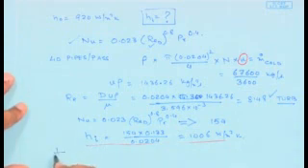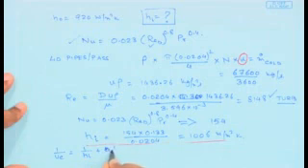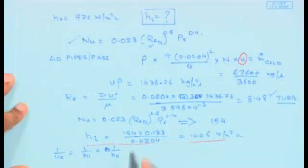So, 1 by UC, the clean coefficient, the overall heat transfer coefficient based on the clean condition. So there is no effect of RD or the dirt factor, it is just the algebraic sum of the resistances of the convective heat transfer resistance on the inside, that is the tube side, and the convective heat transfer resistance on the outside, which is the shell side.